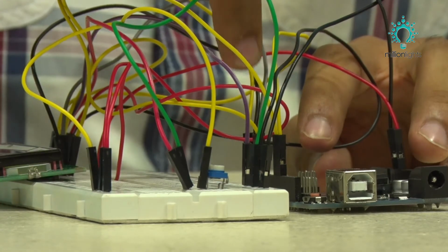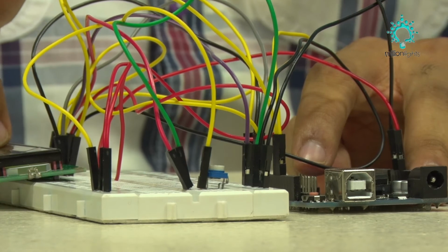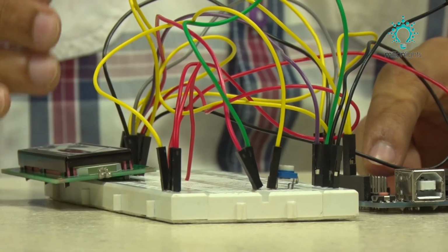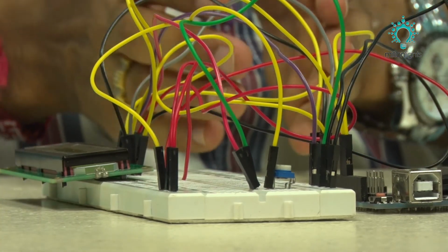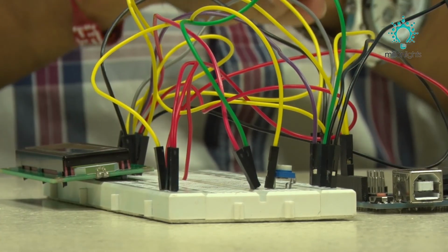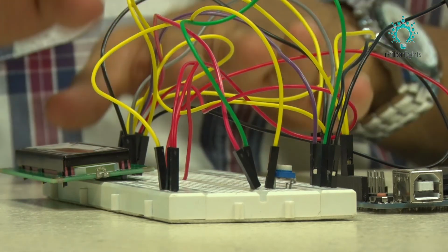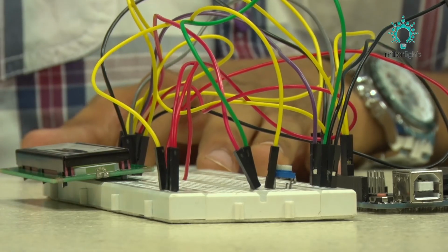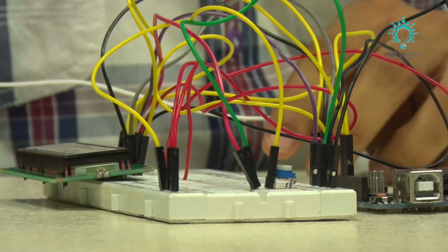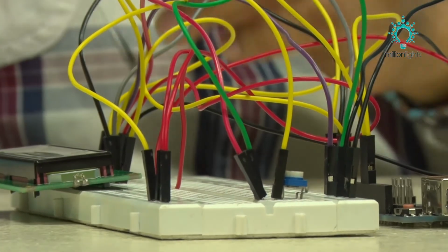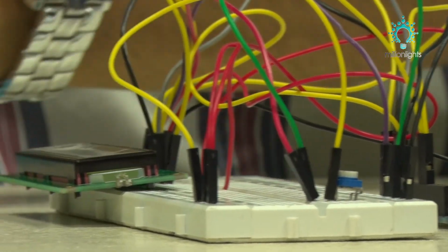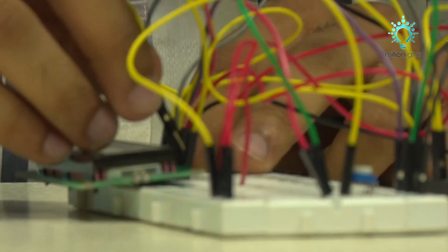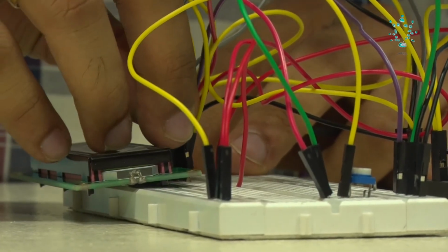So 4 pins from Arduino connected to 4 data pins here and 12 and 11 from Arduino is connected to register select and enable. So these are 6 pins that are connected from digital input output pins from Arduino to LCD, and rest all connections is regarding power supply, that is VCC, ground and all the things. Okay, now 2 more connections are remaining. Those 2 connections are about anode and cathode of LCD. They are used for backlight. So pin number 15 and 16 are left.